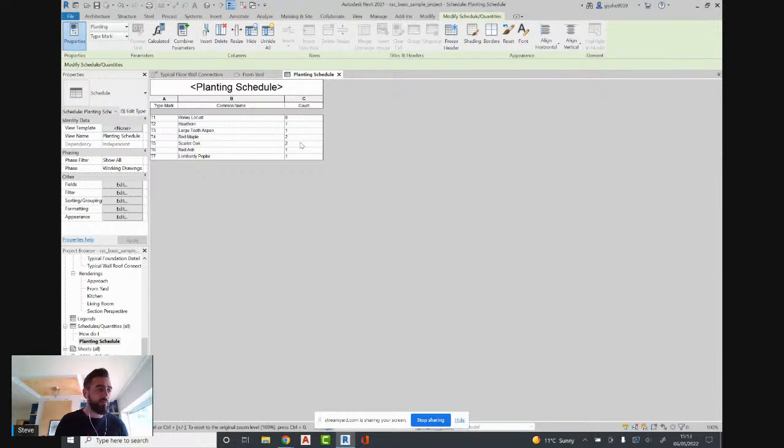So this is great for door details, so door schedules. So you're able to schedule all of your doors in the project. You can say how many door handles, how many screws are within each of those doors. And throughout the project, if you remove a door from the model or add one in, it's automatically added to the schedule.